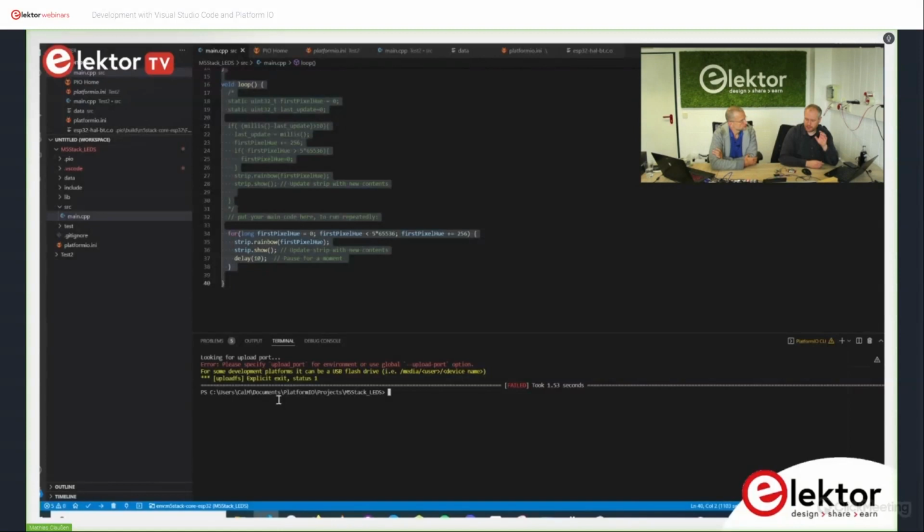Problem here is the way the project is currently set up. For the ESP8266 it is not a problem. For the ESP32, at some points, the action upload file system is missing, depending on how the project is created. It can happen sometimes. It's pio run -t uploadfs as command.